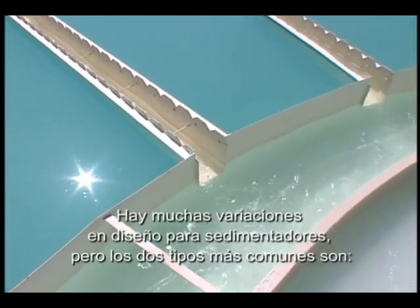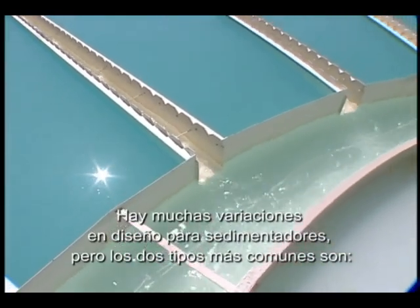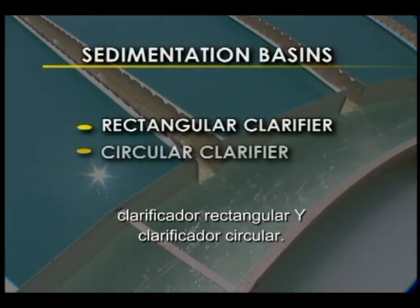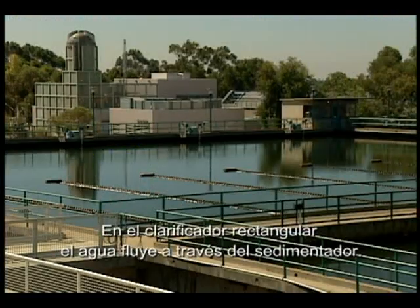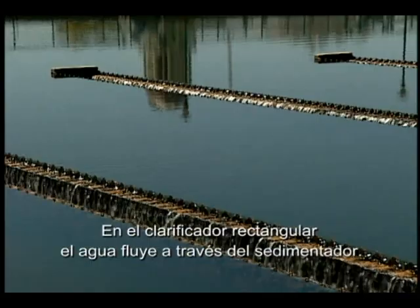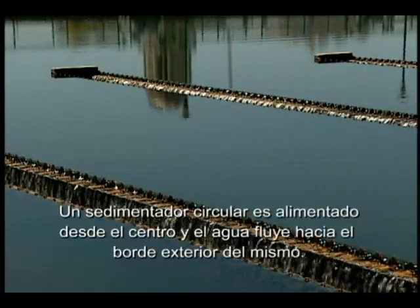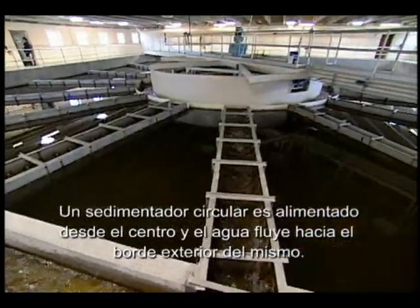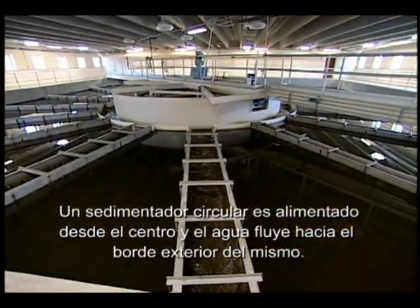There are many variations in design for sedimentation basins. The two most common types are rectangular and circular clarifiers. In a rectangular clarifier, water flows across a rectangular basin. A circular sedimentation basin is fed from the center and water flows to the outer edge of the basin.